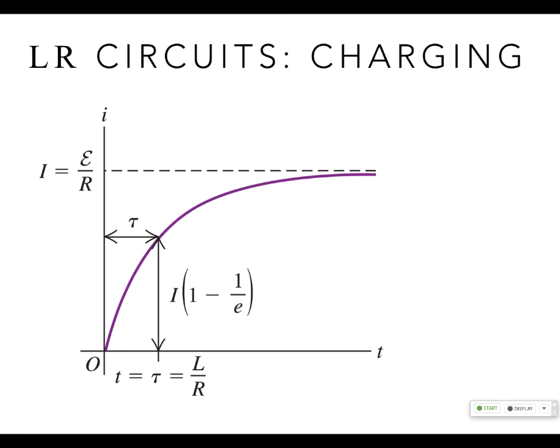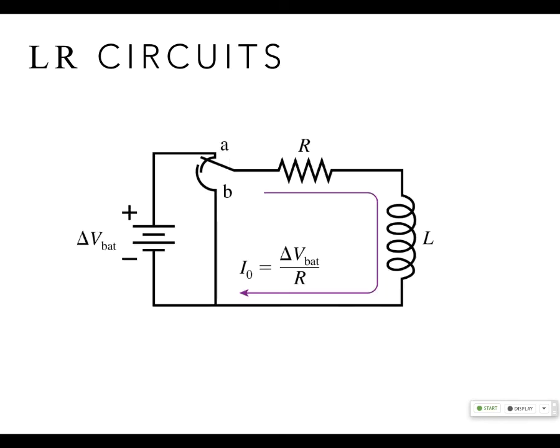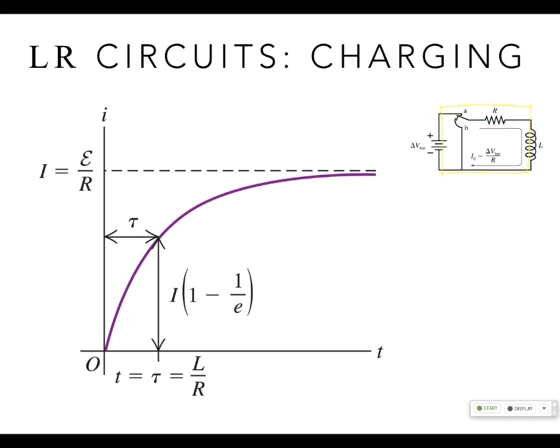So yeah, discharging. This is charging. So when you're discharging, you start with a current. When you're just hooked up here, you start with an initial current and it goes to 0. When you're charging, it starts with 0 current, because as you turn on the current, this thing resists it pretty strongly because you have a big change. And then your current starts to flow. It resists it a little bit less, until you get up to the full current, as if the inductor's not even there. And once the current's steady, what does the inductor do?